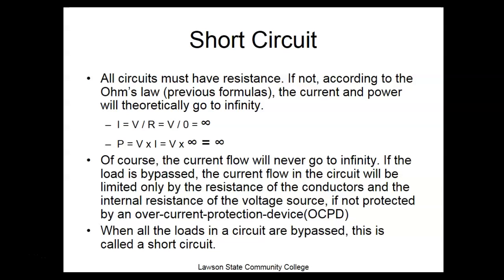But if you go down to Lowe's and look at a 15 amp, 120 volt fuse, and then look at a 15 amp circuit breaker, you'll see quite a bit of difference in the cost. What's nice about circuit breakers is that we can reset them. What's nice about fuses is that they're cheap. So industries are probably going to have more fuses than circuit breakers.